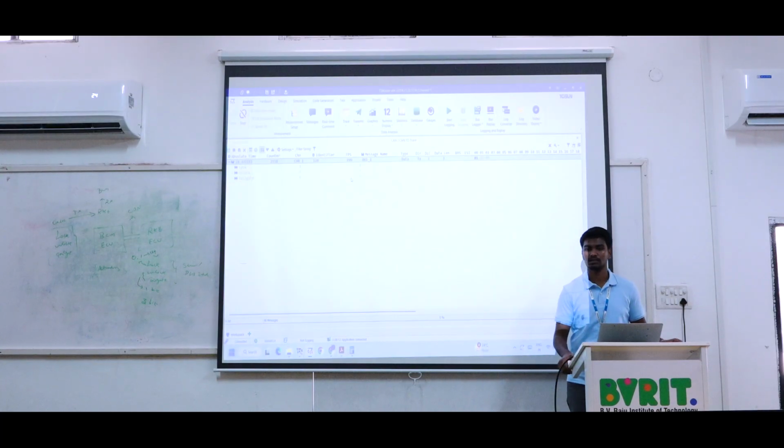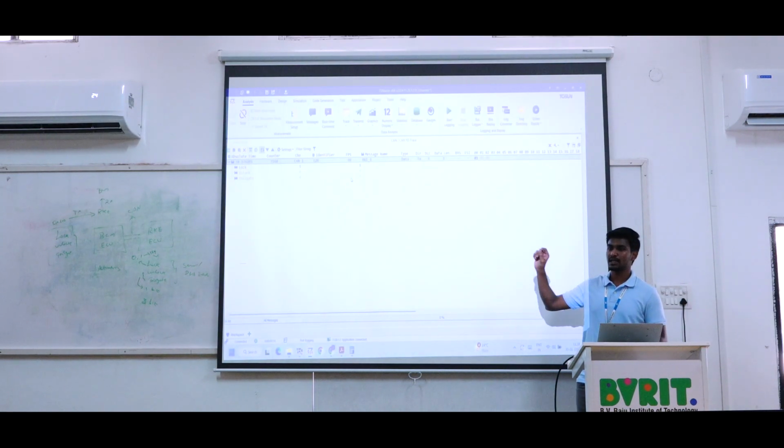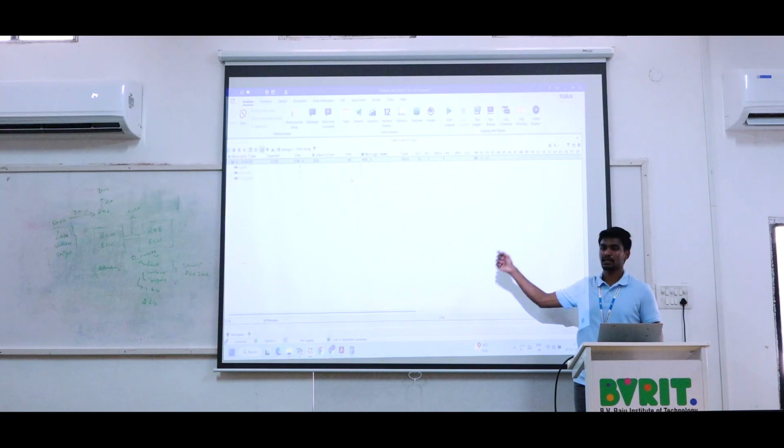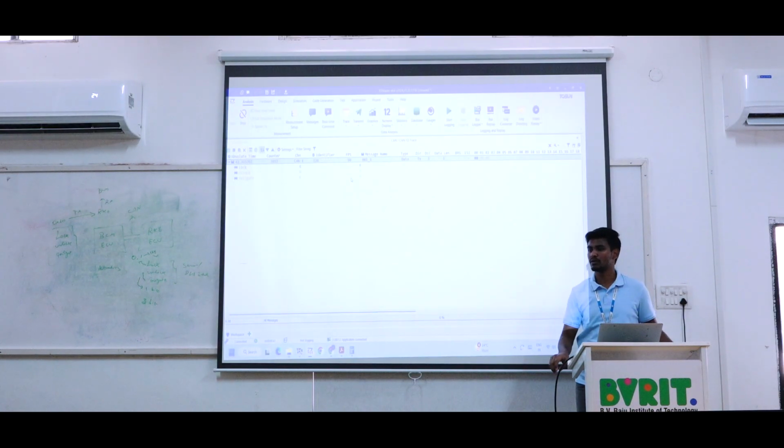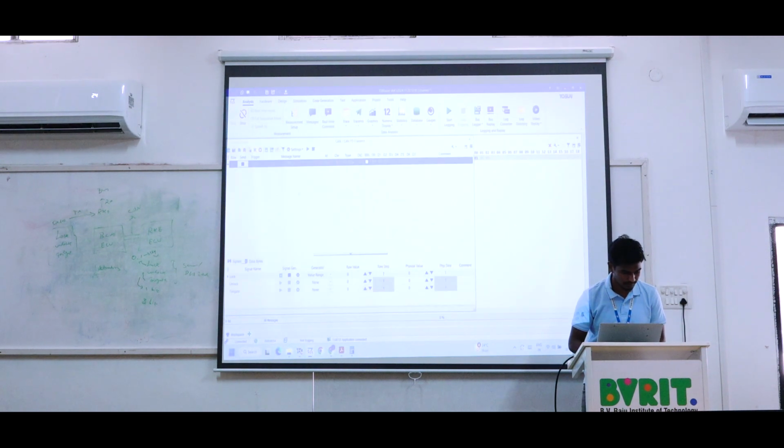This is the advantage of using the CAN protocol. We are not going to lose any data at the time of data exchange. If the message is transmitted 100 times per second, we definitely will not lose data. If it is lost, it will be recovered within 10 milliseconds, so it will not have much impact on any safety purposes. Okay, now I will transmit both the messages.